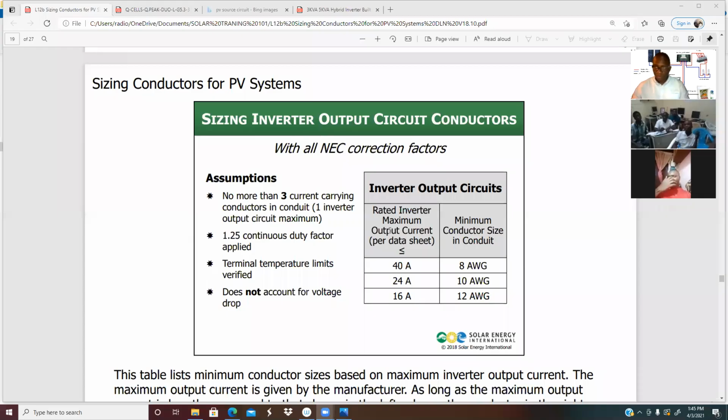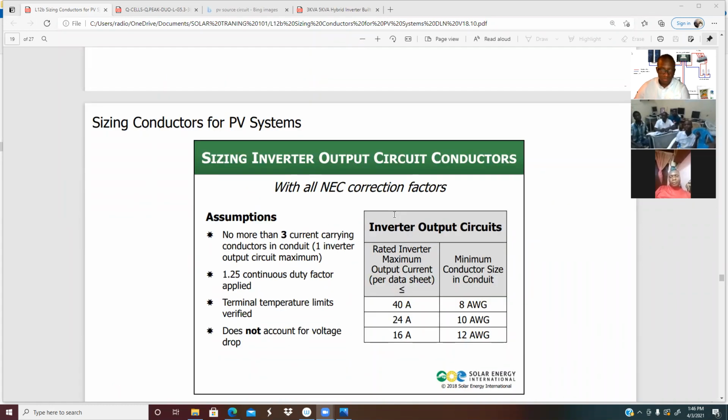You are talking about connecting the two inverters. Do you connect them in parallel or in series? The two inverters can go in parallel, not series. If you want to get the two hybrid inverters to 10 kVA, you have to parallel them. You don't do series because it doesn't work with series. You have to go to parallel.